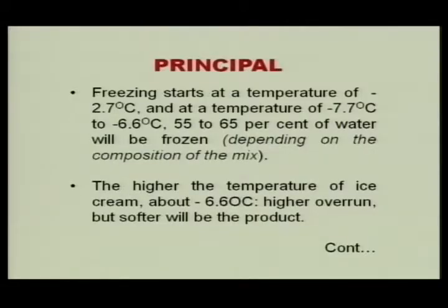Now, we remember that the freezing starts at a temperature of say -2.7 degrees centigrade, and from -7.7 degrees centigrade to -6.6 degrees centigrade, around 55 to 65% of water will be frozen. Now, this will depend upon the composition of the mixes.